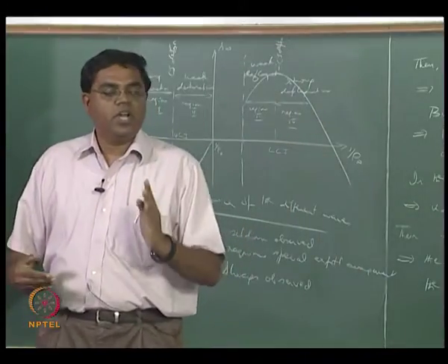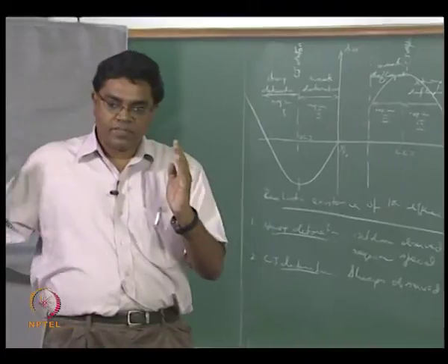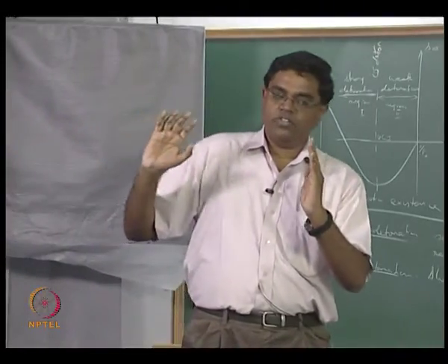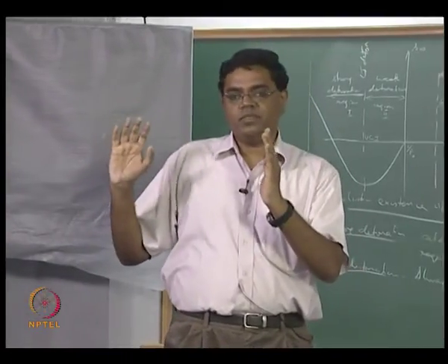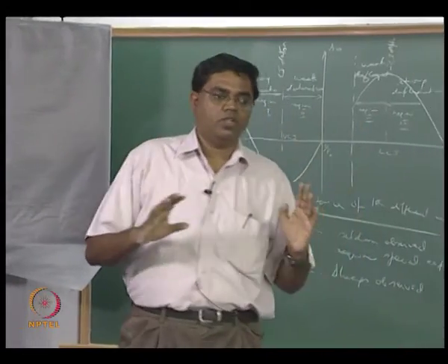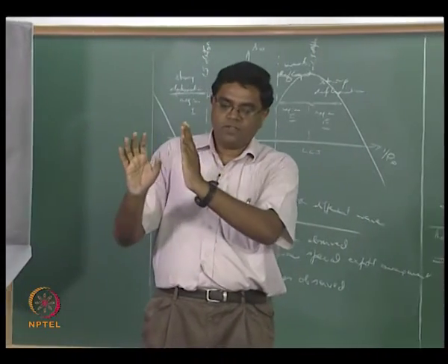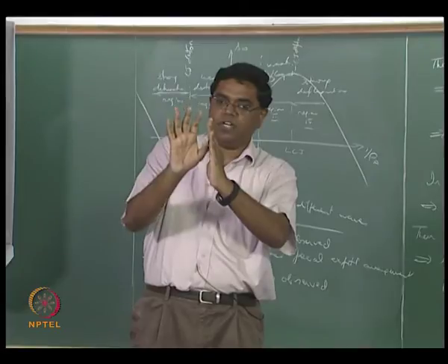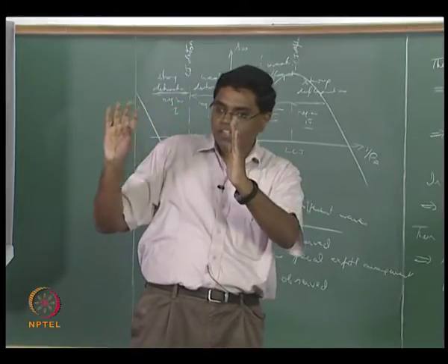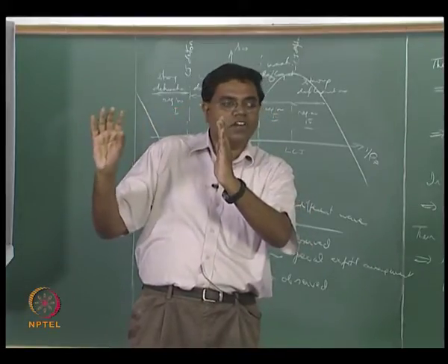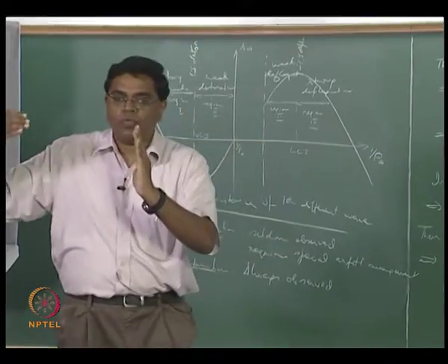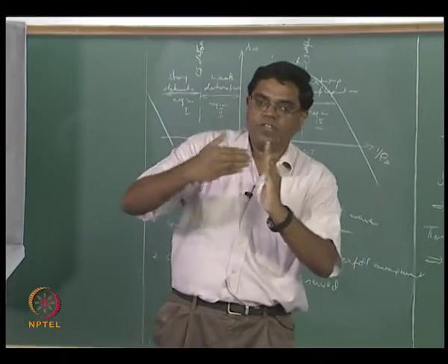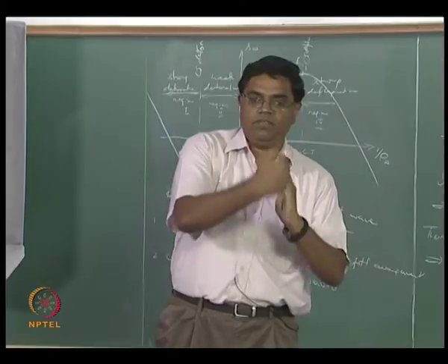Typically what then happens is you now have an expansion fan, shouldn't say fan, you should say expansion wave, because we are basically looking at one dimension. So you now have this wave that goes like this, and then there is a pressure buildup, and that also propagates, so you have an expansion region that's getting created, which can propagate through this and then go and try to weaken the wave.